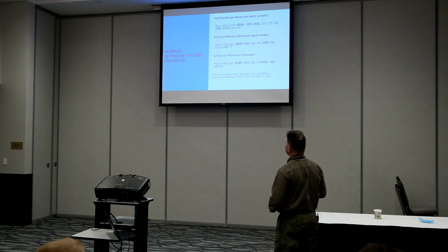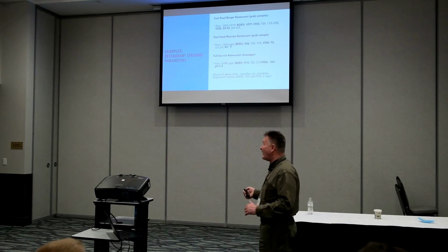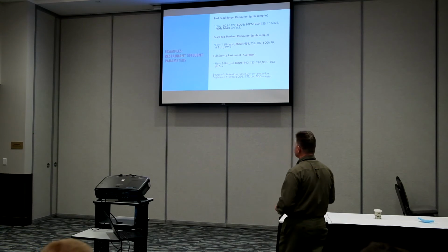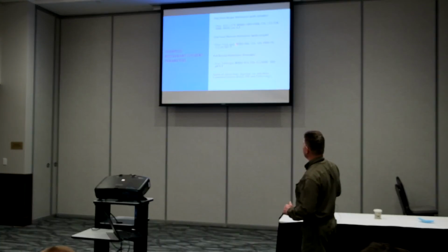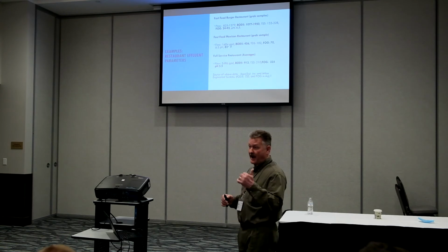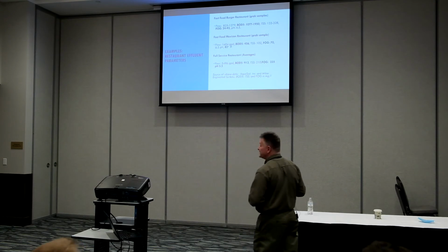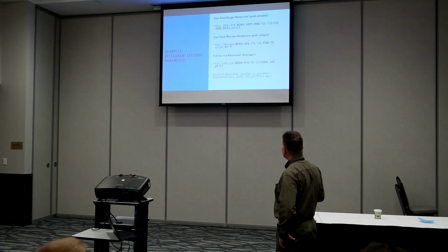You look at the fat, oil, and grease, pretty high. What did I say? After about 25 to 35 milligrams per liter, we really have to start watching it. Something this high is really going to start clogging up our soil system. Fast food Mexican restaurant, BODs are relatively low on this particular restaurant, about 456. Oftentimes on some of the ethnic restaurants, like a Chinese restaurant, you'll see very high BOD numbers. Fat, oil, and grease is 70 coming out of this facility. Now, full service restaurant, we have a BOD of 900, so say 1,000. But look at the fat, oil, and grease at 235, and look at the pH, it's way down.